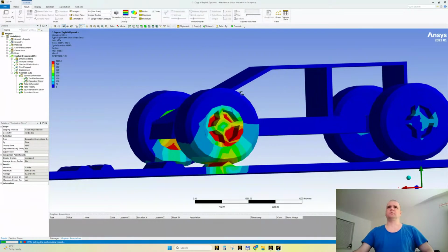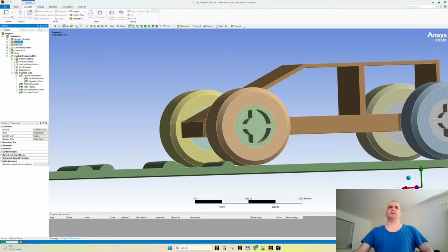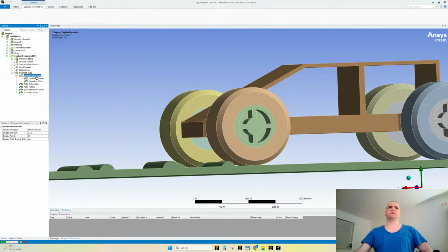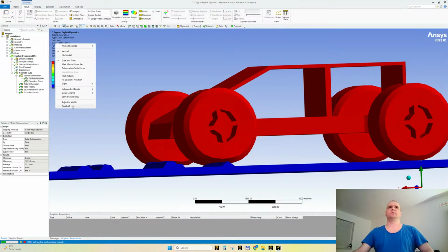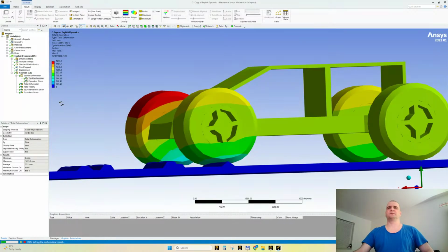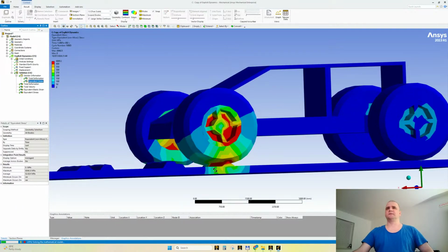And gradually I would use nonlinear materials for where I have metallic parts. So instead of aluminum alloy, choose aluminum alloy NL, nonlinear, from the engineering data library, which you already know and use. So the tendencies are very nice.